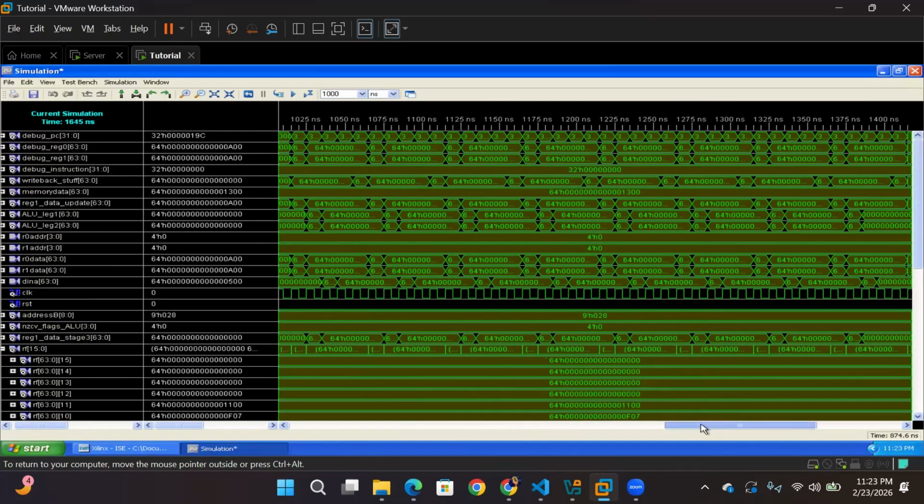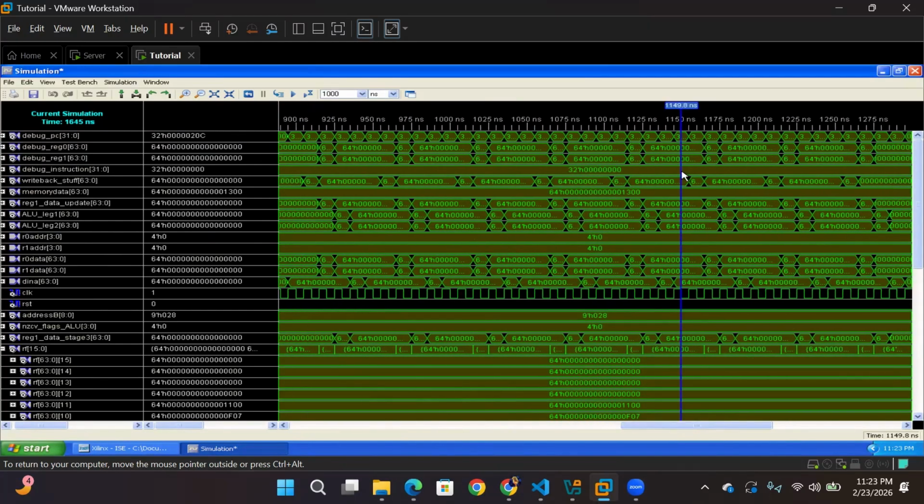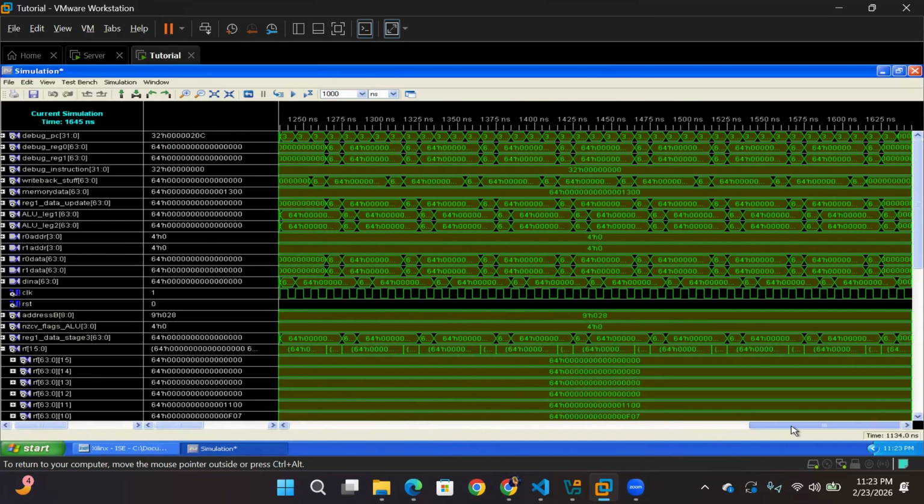So basically from the registers, the data is being stored onto the memory. If we keep running it for some time, the register contents are all going to be 0, and we will get data in the memory, which confirms that STR instructions also work.